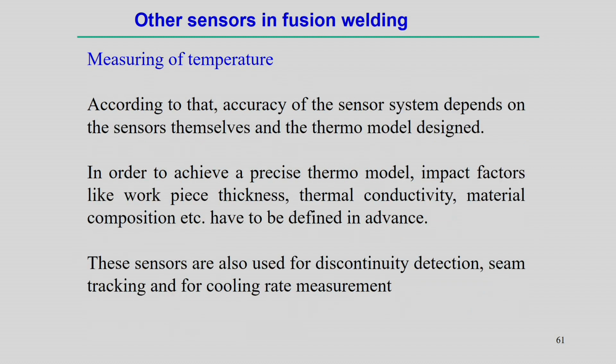So, the accuracy of the sensor system depends on the sensors themselves, and of course the thermal model design. That means we are capturing the data, but how can we convert this thermal image into a temperature? That needs some kind of model design. In order to achieve a precise thermal model, impact factors like the workpiece thickness, thermal conductivity, metal composition, etc., have to be defined in advance, and accordingly we can make the model such that we correctly measure the temperature by looking into all these factors.